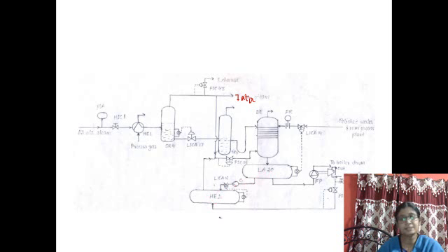For a heat exchanger there must be a heating media and a cooling media. The cooling media is the cold water flow from the storage tank. This is the suction pump, symbol C1, and there exists another level control loop, LICA 16. This LICA 16 is for measurement of the tank level of HE2.